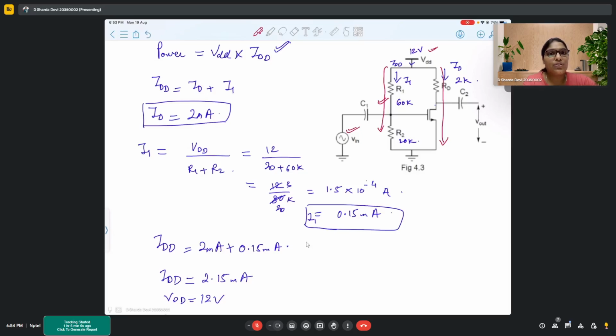To be very practical, the maximum gain that you can obtain from a single stage MOS amplifier is around 60 dBs theoretically. Practically it would be even less, around 50 dBs. And for that particular gain, the output swing that you get is very small.